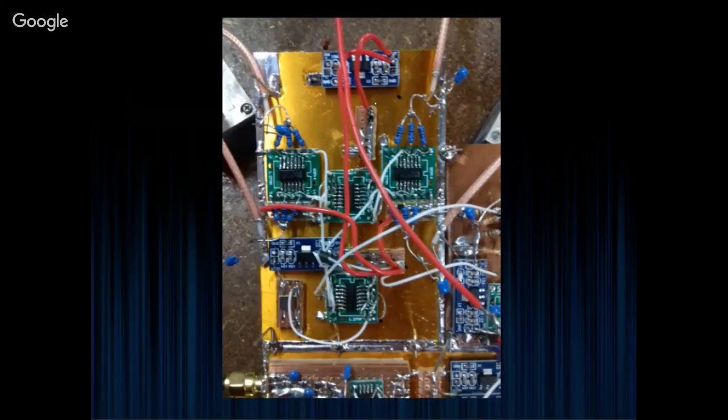What's important is to ensure you have continuity of ground plane first and foremost in, I'd say RF prototyping, but digital as well, to preserve the integrity of the signals, particularly when you're driving square waves. People think, well, 10 megahertz, 40 megahertz, 100 megahertz isn't much, but they might be forgetting about the harmonic content that can stretch up into the gigahertz. So yeah, continuous ground plane.